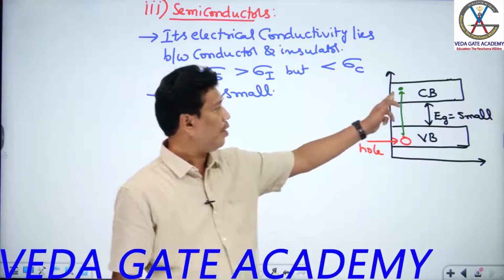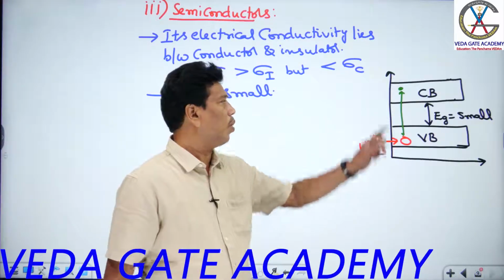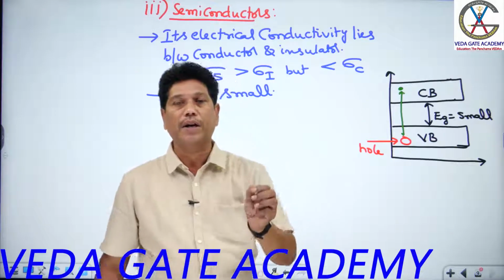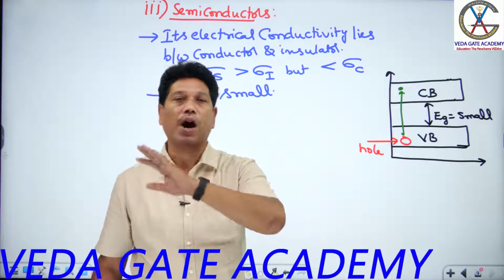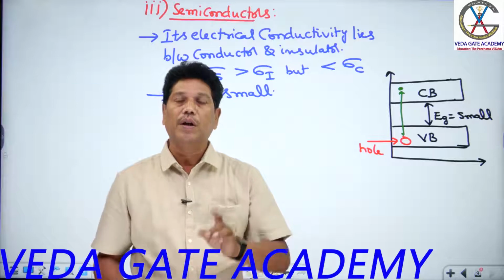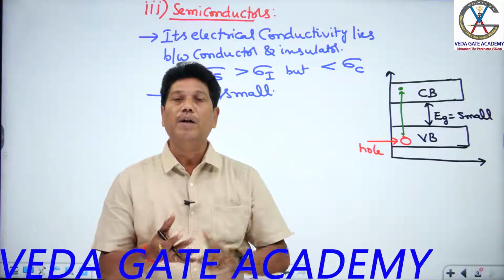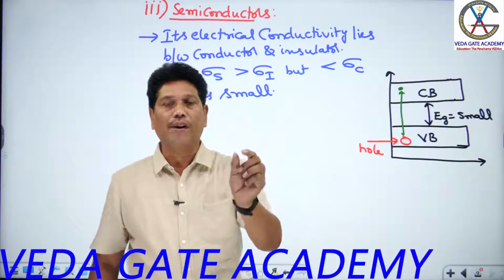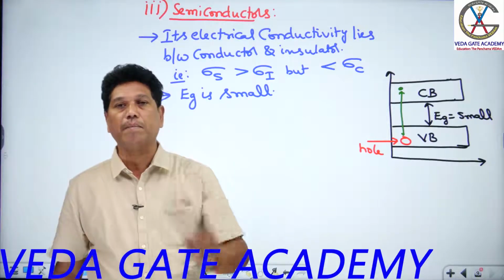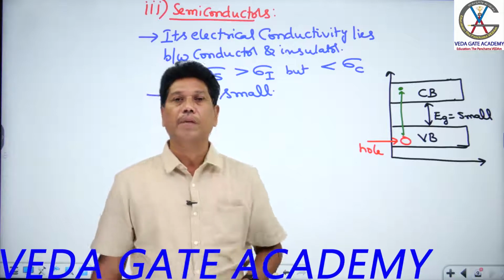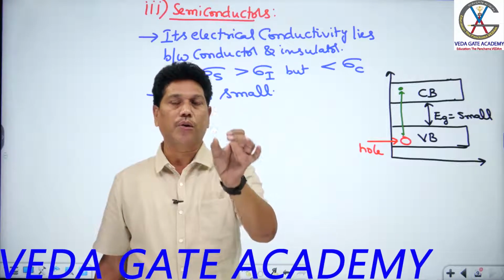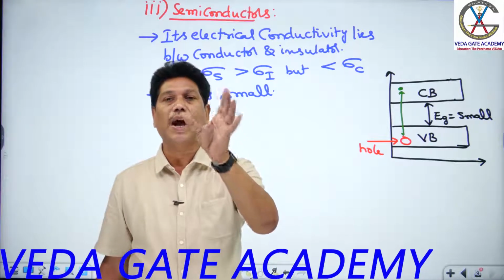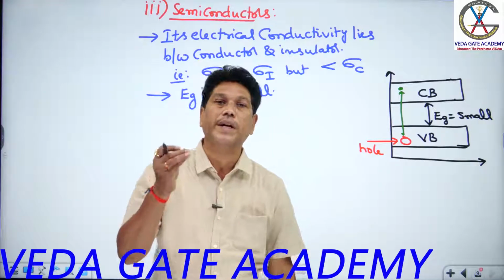Okay, and one more thing you remember here. The electron that enters the conduction band, does it stay permanently there? No. Understand my point, students? After jumping to the conduction band, the electron can spend only a certain finite time in the conduction band. Don't say permanently. Sir, how much time can you say? That is called the carrier lifetime, denoted by tau.